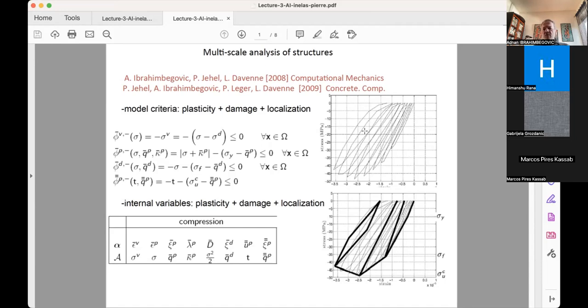So the main goal for us was to be able to represent a typical dissipation that is taking place in one of these hysteresis loops. The hysteresis loop being this nice eggplant type of shape, you can obtain a corresponding area. And in order to make our computation robust, we took a linear hardening or linear softening, which amounts only to one iteration. You're sure to converge.